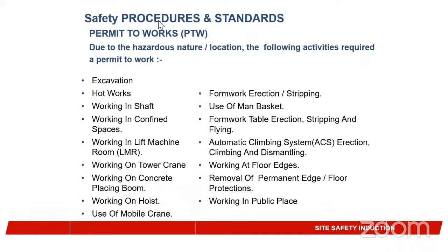That's why we tell them, whenever you want to start your work, write your name on the permit to work. Some of them will not write their name on the permit to work. They will start going. They will say they are busy. They want to start work early. If an accident happens and you get involved in that accident, what the company will say is that your name is not on the permit. They never permitted you. So there are ways that we can communicate the purpose of this permit to work.